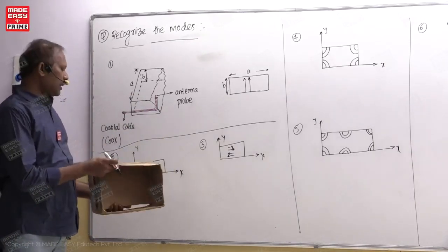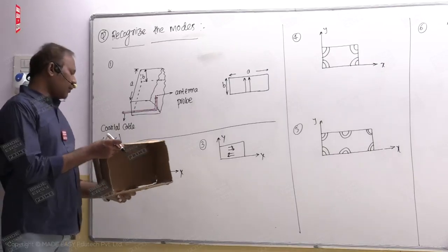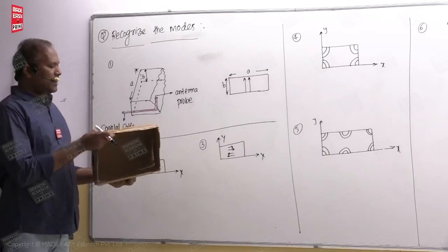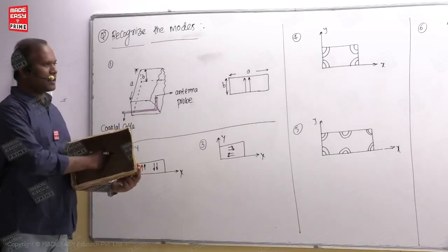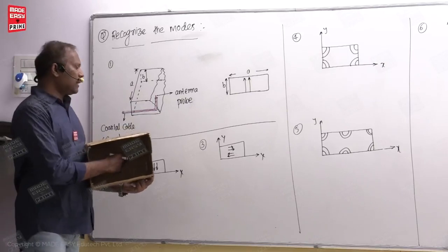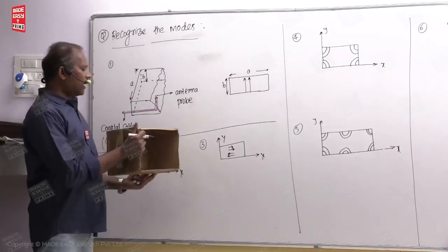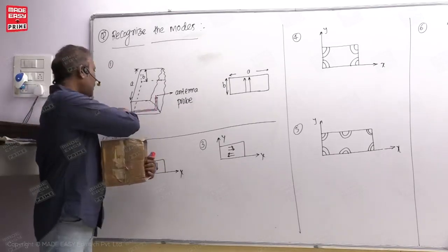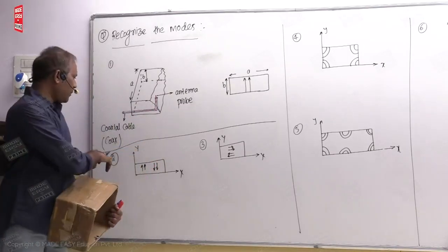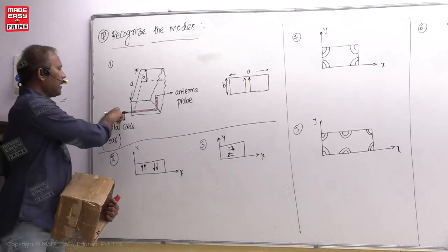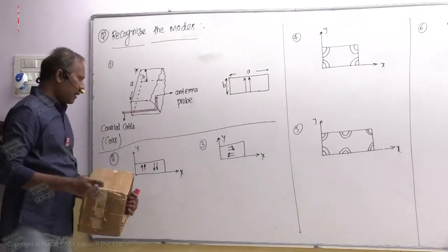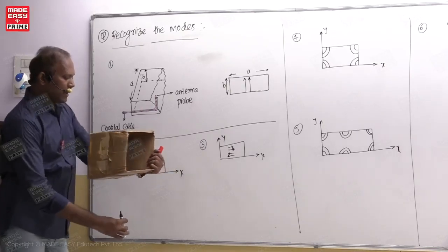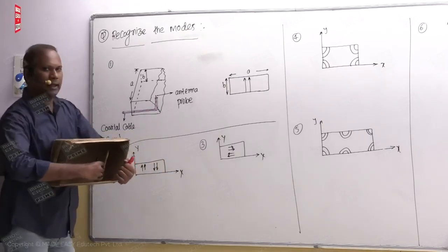Of course, this end is open, and for excitation purposes they close this end and make it a short circuit here. Short circuit means a conductor surface. Then they take a coaxial cable, short name coax, which comes inside like this through a drilled hole and enters the waveguide.